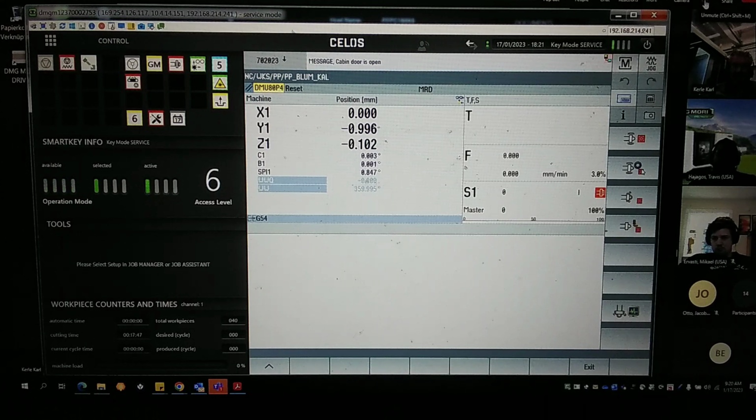Okay? Why? If a percussion of this size happens, let's say like a crash, we have not to take care like with an emergency stop, we twist or we tilt an axis, or a tool maybe is broken, or we damage the surface of a workpiece. In such a case, if you have a crash with 20 G acceleration, then the machine is damaged much more, okay? So therefore, we immediately power off the system, okay? That's the reaction. Okay, so far so good?